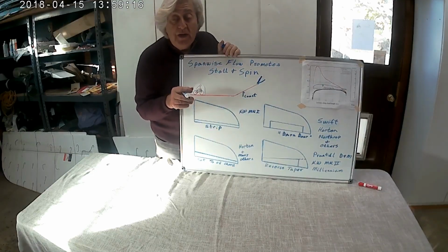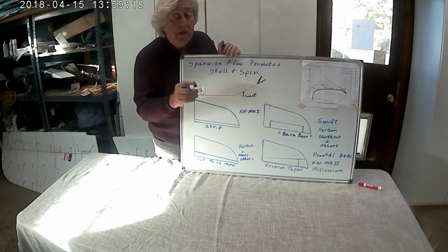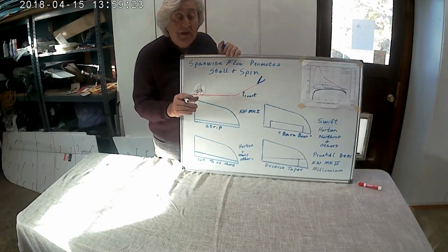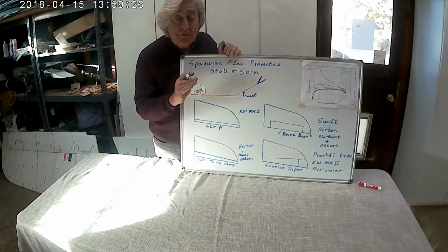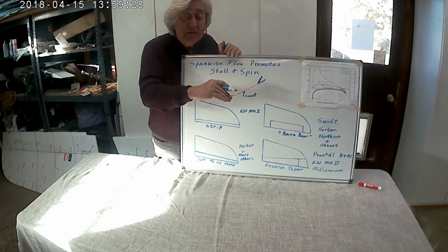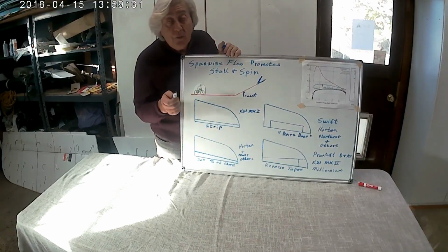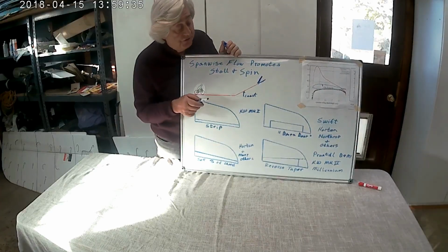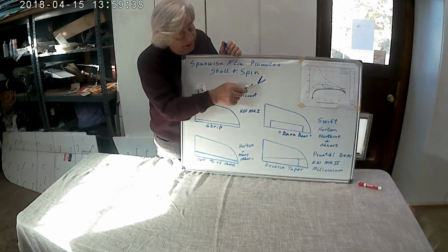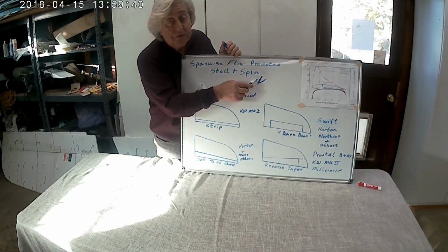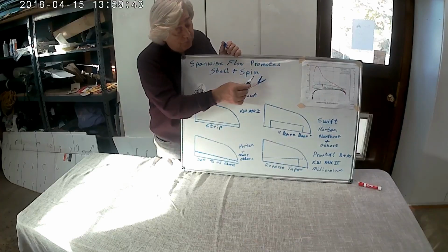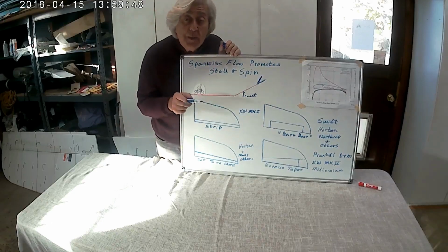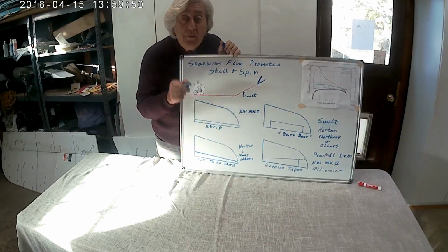Now, when we add turbulators, or when we make a lump on the elevon, or when we make the elevon thicker than the main wing area, what we're doing is we're forcing the flow to re-accelerate to try to keep it attached to that control surface. And it works to a certain amount, 10% or whatever, but that wasn't enough for my solution. So here we have a situation where deflecting the control surface will force it upward, will force spanwise flow, and that's bad. But it didn't happen for the reverse taper elevon. And why is that?